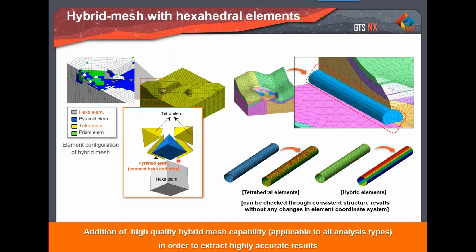When you use hybrid elements, the number of elements is low and the computational time is very fast, so you can get the analysis in much less time compared to tetrahedral elements. This is one advantage over Plaxis. As you know, hexahedral elements are more accurate than tetrahedral elements because of the greater number of nodes. In addition, you can use higher order elements as well, wherein you can go for mid-side nodes to have more accuracy in the model.